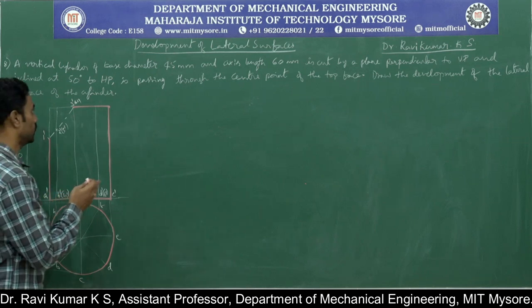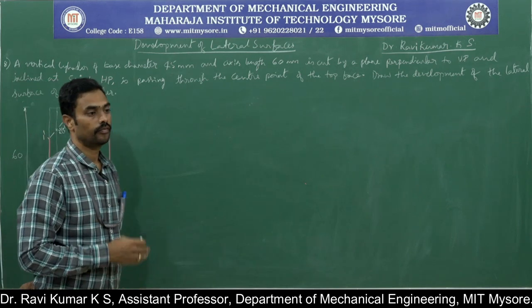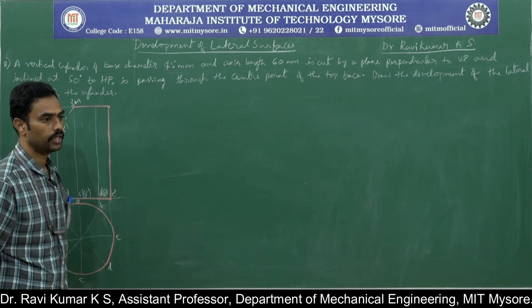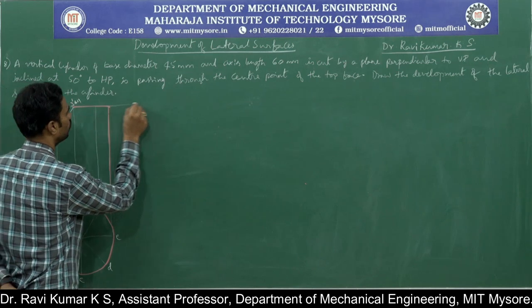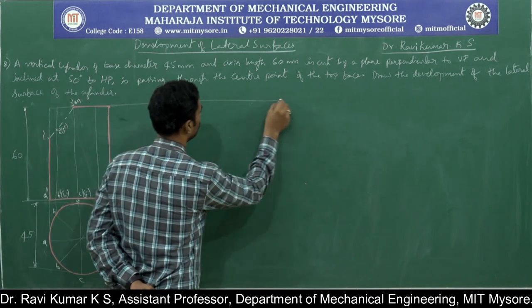Now since it is the case of a cylinder, we need to draw the development using the parallel line method. So I will take the extended line here.